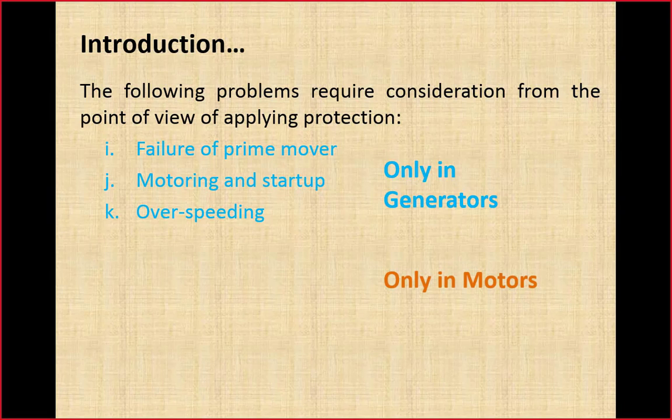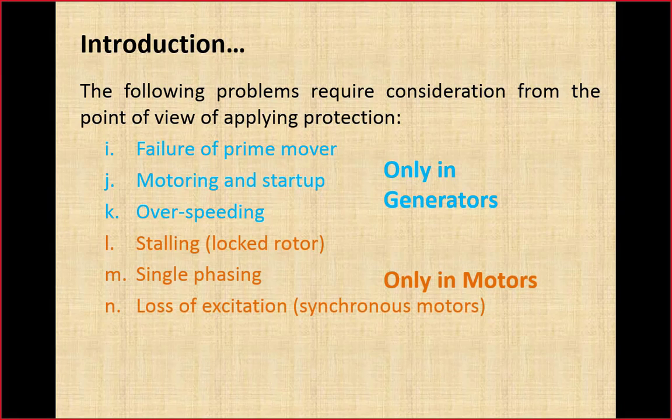And following problems are only associated with the motors. That includes stalling or locked rotor condition, single phasing in case of a three-phase machine. If one of the phase is broken, machine is now live only on two phases, that is known as single phasing. Loss of excitation, this problem is only associated with the synchronous motors. Loss of synchronism, this problem is also associated only with synchronous motors.